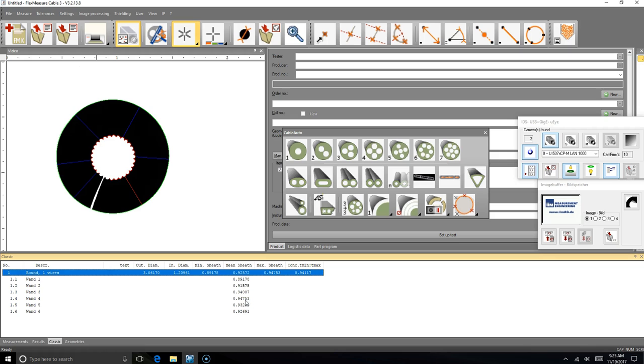It would be right here. And these kind of go around this orientation. So how this measurement system works is it takes a measurement from within 60-degree segments, which is a standard with cable manufacturing. Within this 60-degree segment, it's looking hundreds and hundreds of times, maybe even thousands of times, looking for the min or the max wall thickness here. So it's looking for the minimum wall thickness here. And it goes around and looks in this 60-degree angle, on this 60-degree angle, on this 60-degree angle. So that's what it's doing.